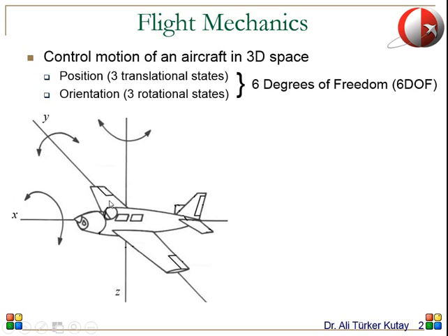Okay, so then what you do is, if you want to go up, for example, if you want to move along the Z-axis, which is the climbing axis, you cannot really move an aircraft directly along that axis. So let this be an aircraft, okay? So this is the x-axis, it needs to be moving at all times. So you cannot really move it along z-axis directly. So what you do then is you rotate it first, okay? And then its velocity gets a component in the vertical axis. That's how you get the climbing motion, if that makes sense.